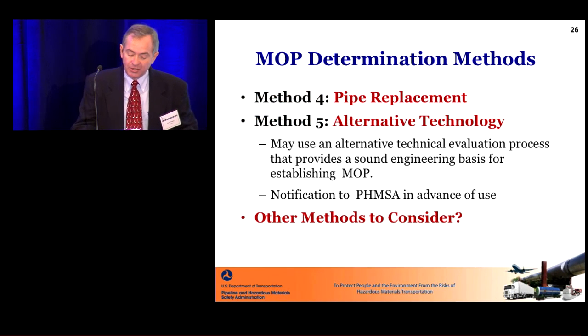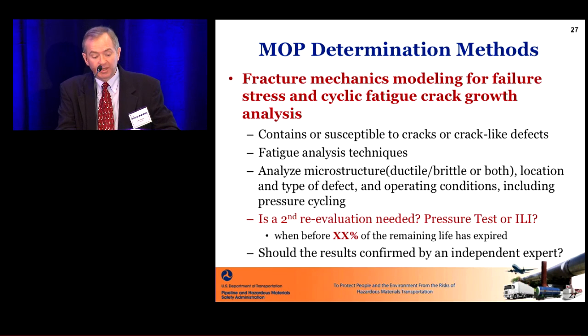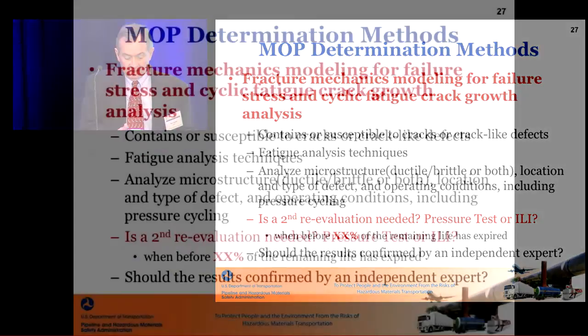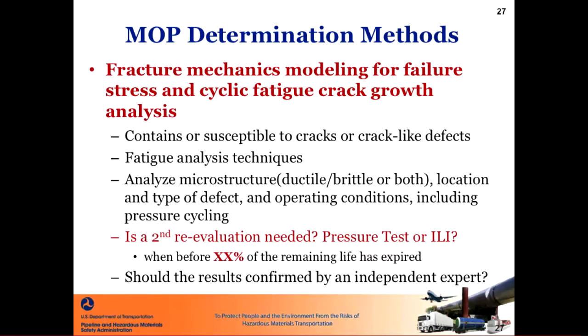MOP determination methods: again, fracture mechanics modeling would need to be part of that for your failure stress and to look at your cyclic fatigue crack growth analysis. And you can see here, these are the type of things we would want to look at: what type of fatigue analysis techniques do you use?